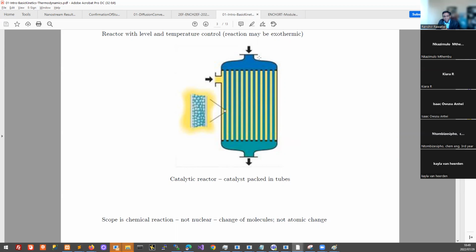So we can change how fast we are feeding that reactor. But the other thing we could do is also change the length of those tubes. So maybe this is 5 meters, and then we realize, well, if we go as long as 5 meters, then we start to get the unwanted products. So we need to cut back to maybe 3 meters or whatever it is.